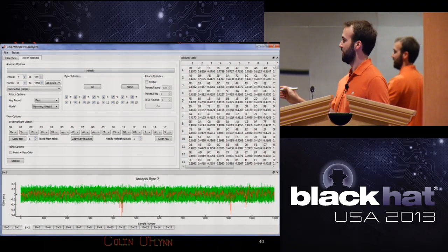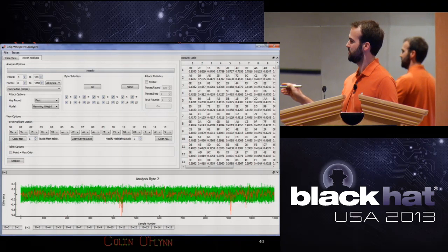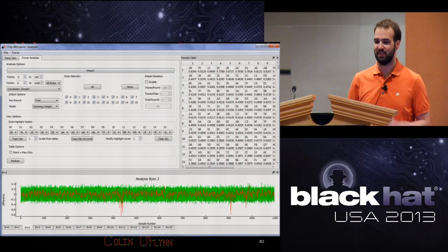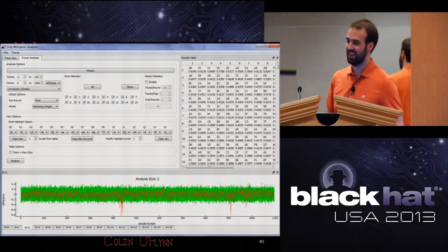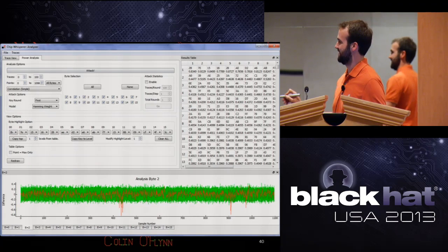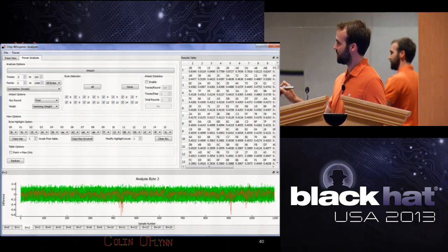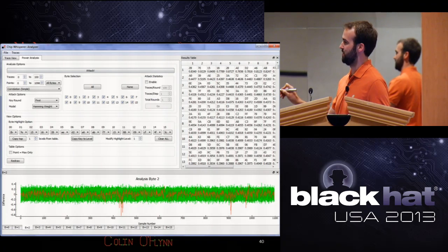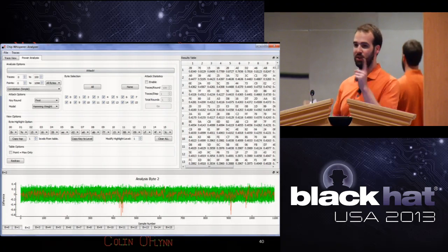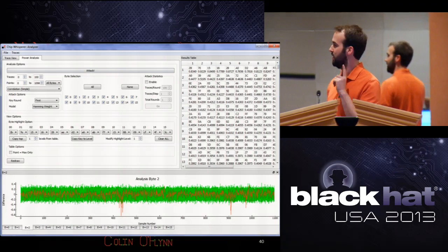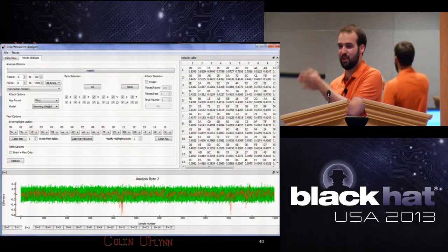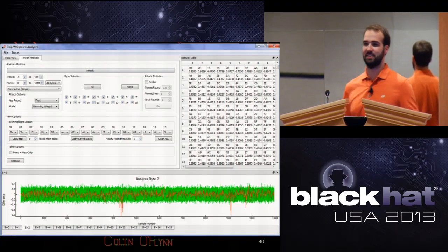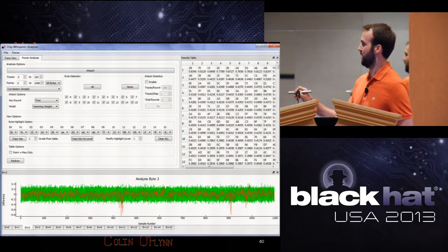And then once you know that, you shift everything, can you just delay the capture? At this point, I don't know. The hardware works. Until recently, you couldn't do that with the hardware. I added that, but I haven't tested it well enough to do it live. So you could say, I'm going to save time, and you literally only need one sample. If you could sample the right point, you just need a sample and hold system. You don't even need an ADC. But because you don't know the point, I just do all of them.